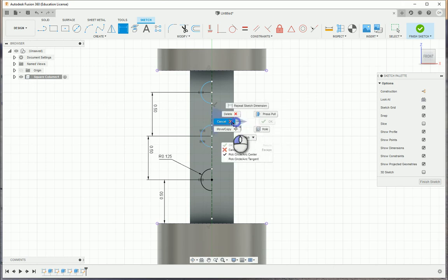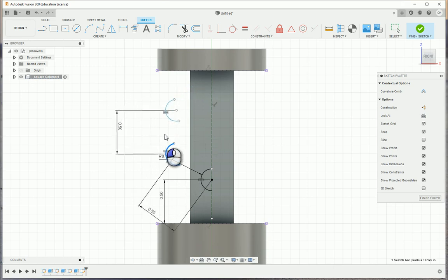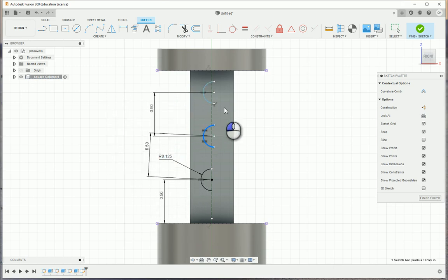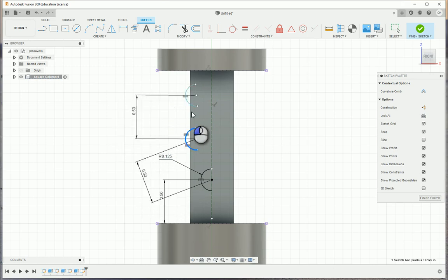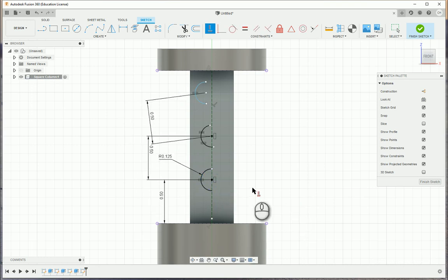Okay, now the only issue is as we do that, you'll see here, I still see blue arcs. Here's the thing that sometimes happens, anytime I tell students you see blue lines, click and drag and see how they're moving. So here I can click horizontal, vertical, choose the center point of this arc, and choose the center of the bottom arc. Same thing from here to here, and that'll work out.